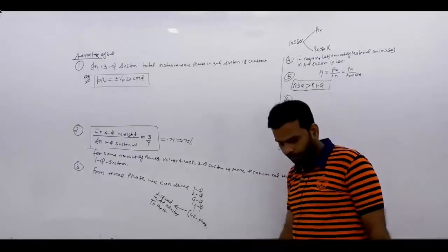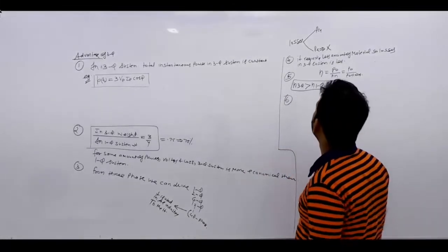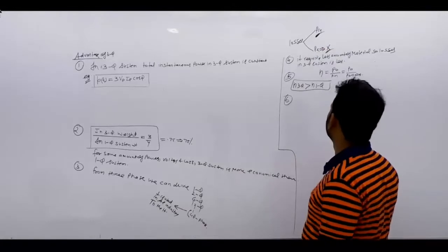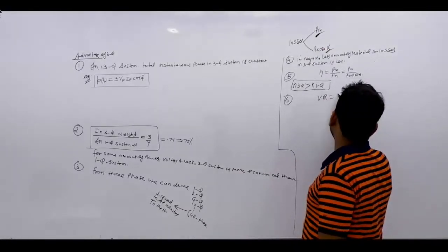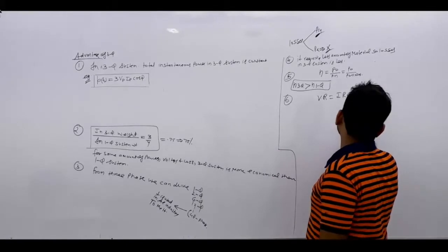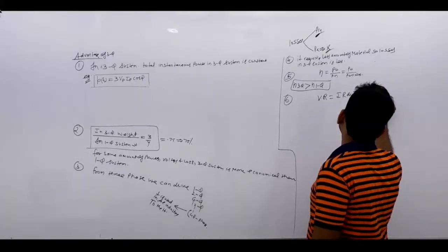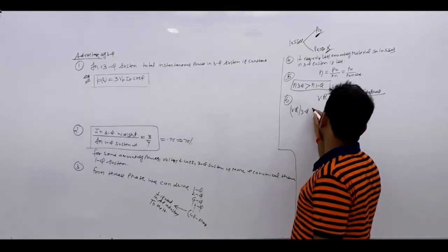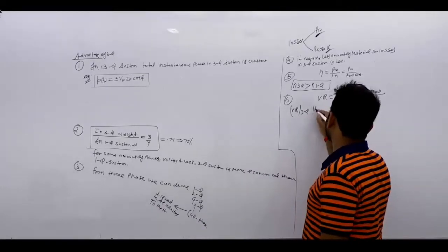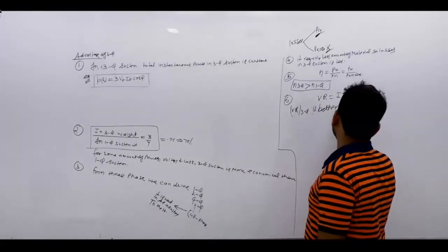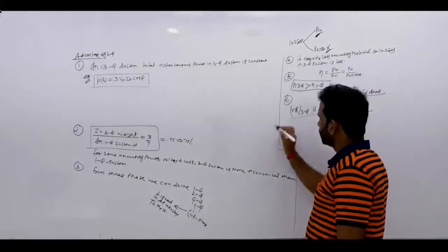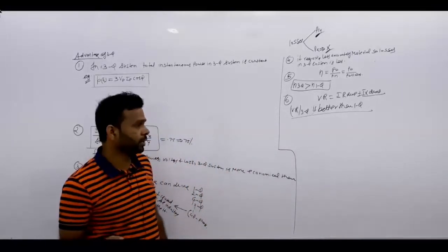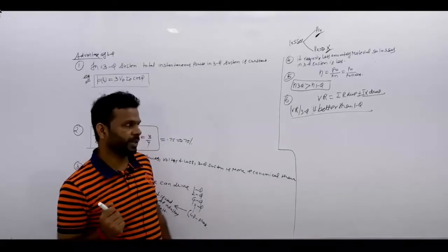Now since the copper losses are less and losses are also less, so if you know the voltage regulation is what? IR drop plus minus IX drop. Okay, so the voltage regulation of three-phase system is better than single-phase system. Okay, just because of material we have more efficiency, better voltage regulation, and low losses. So these are the 6 advantages.